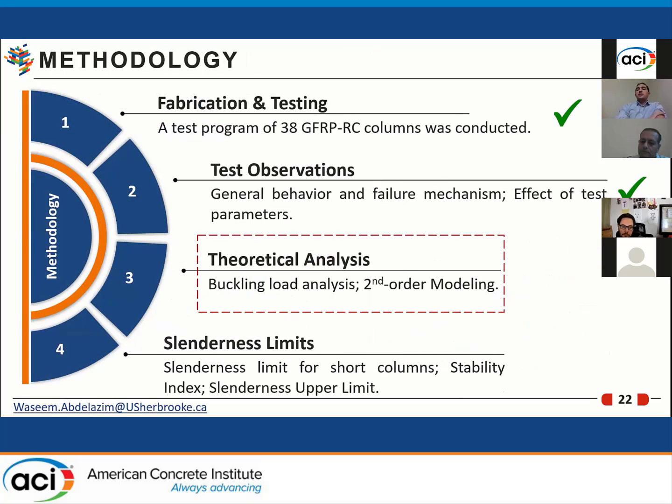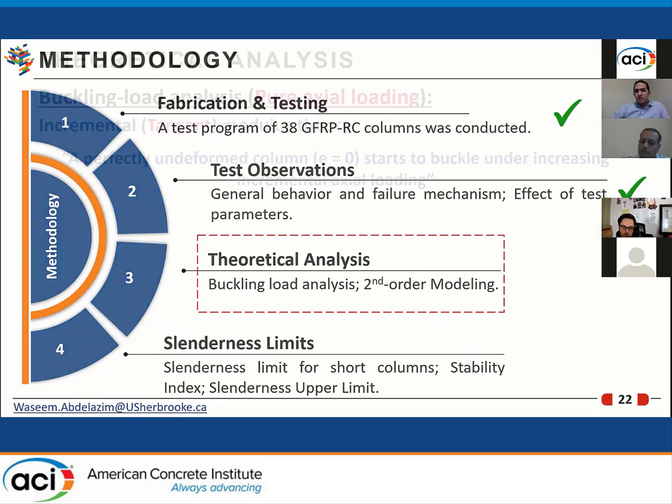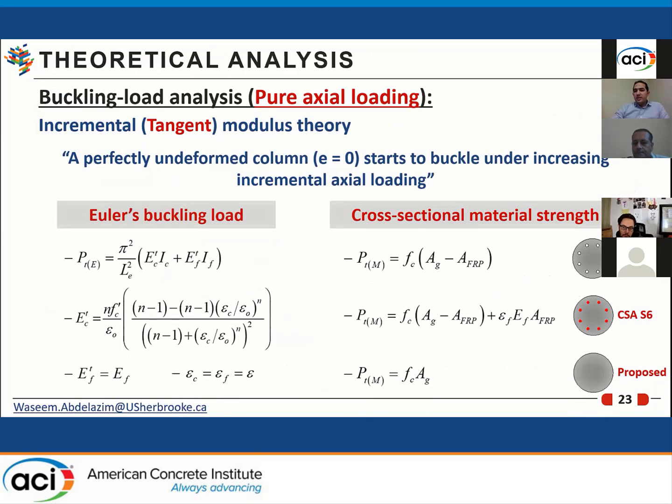The next part is the conducted theoretical analysis. The theoretical analysis conducted is divided into buckling load analysis and second order modeling. Buckling analysis was performed considering the tangent modulus theory based on Euler loads.